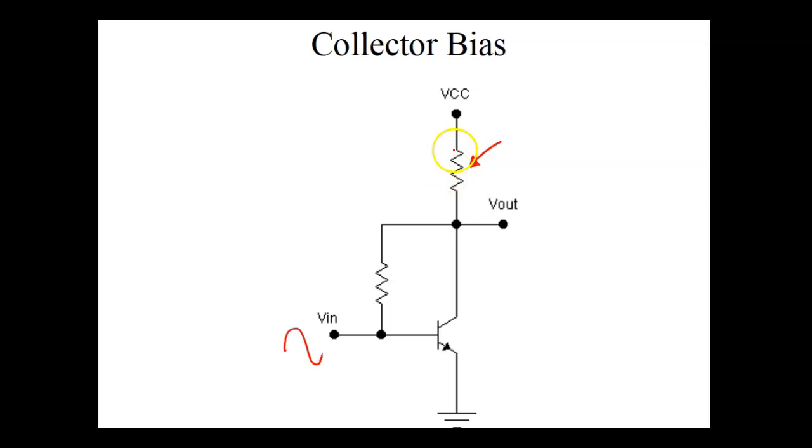So this guy right here, if I set a 1K and this was a 1K, and of course this drops 7.7 volts, then if this is 10 volts, then this would be, I'd have to think about it, 4 point something, and this right here would be 4 point something. But this guy right here is setting the primary voltage that's going to be applied right there, right?